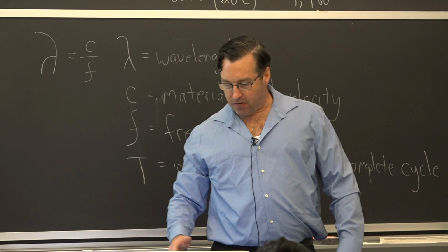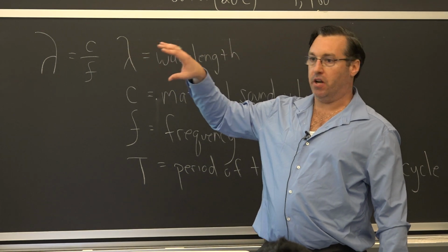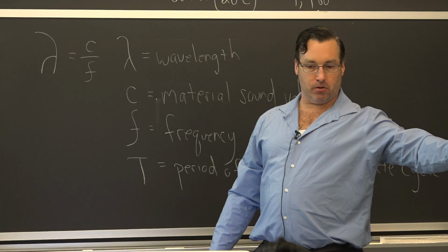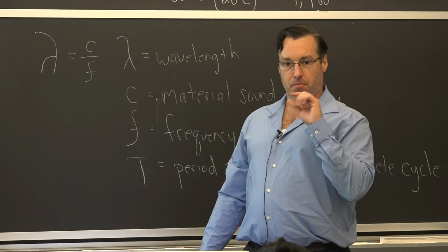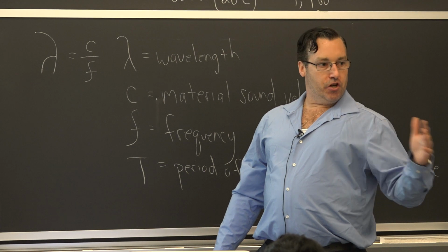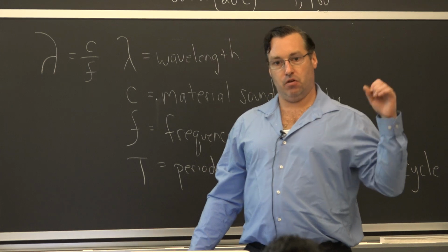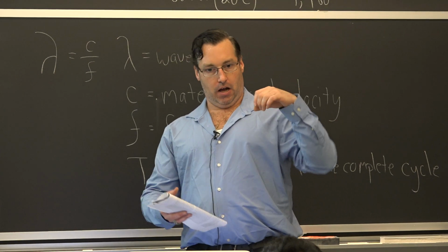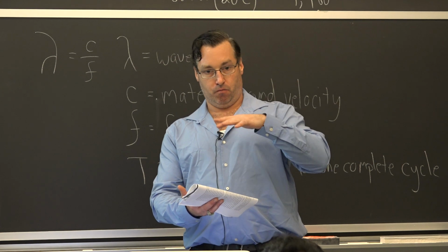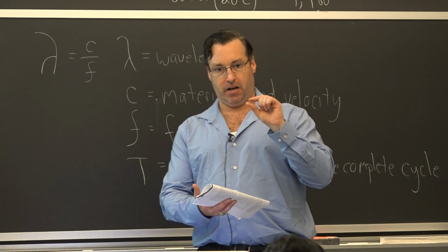So we discussed most of this already. The main advantage is that it can find deeper internal flaws. So if you were trying to find thousandths of an inch, or mils, you would generally use an eddy current technique if you knew it was a surface flaw. So say you did shot peening or some type of laser operation to get a compressive residual stress layer in the component, like they do with glass. You have a compressive layer.